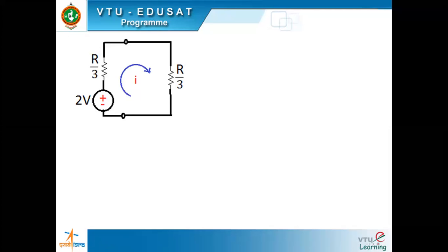But as of now, they can sometimes club the theorems like this. In such cases, we should be a little smart to understand that if the maximum power has to be transferred to the load, the impedance should be equal to the impedance that we have found out by Millman's theorem, or the Thevenin's resistance.